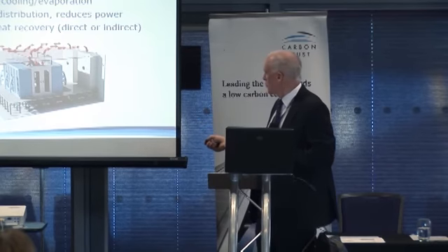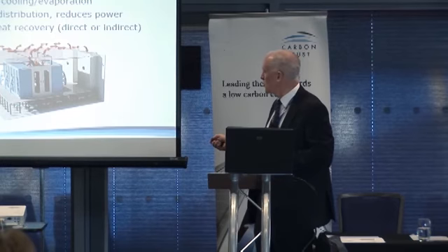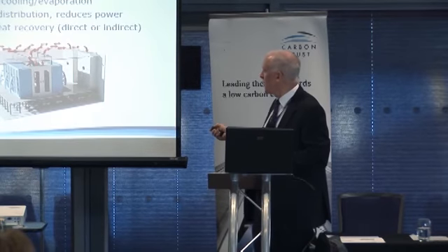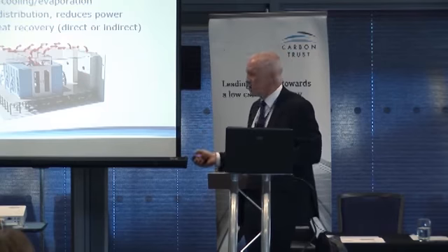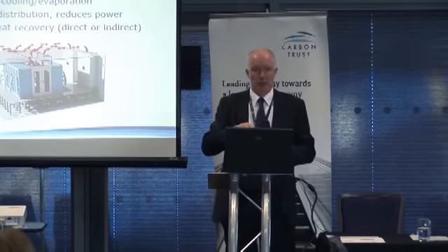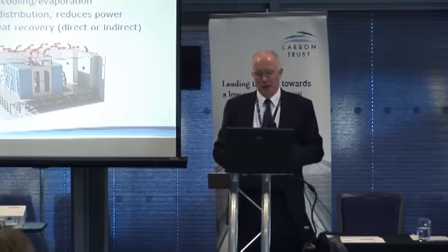Hot air here, the room is used without very little disruption to the cold air, so the whole room is cooled, which makes it quite a nice environment. The cold air goes on, but the hot air is taken away by enclosing the aisle and taking it away through the roof back into the top of the unit to come out as cold. So simple containment like that can work very well.